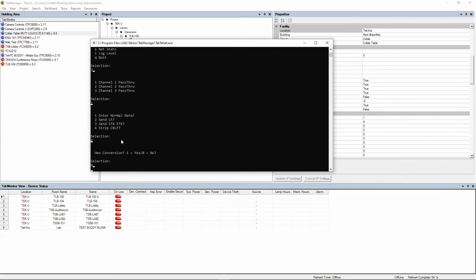And after this, you can type in any commands you want, and you'll see whether or not the device responds to them. If you want to exit the serial pass-through mode, just type in 3 X's and hit enter, and it will take you back to the debug menu.